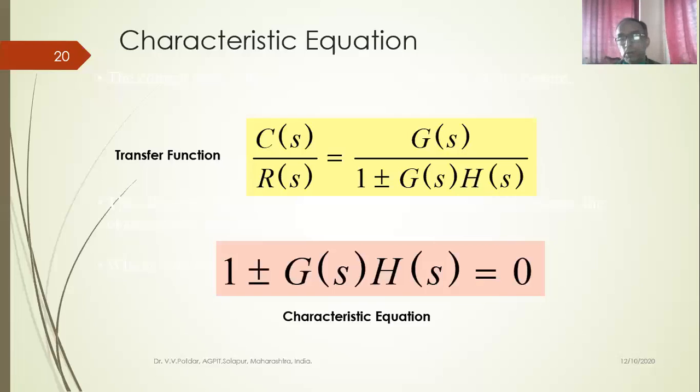All those values of M, K, and B we can suggest to the designer, so that once the suspension system is designed, and if the values of B, M, and K are selected within the designer specified range of values, when it is actually manufactured and actually used, I'll be getting stable behavior of that suspension system.